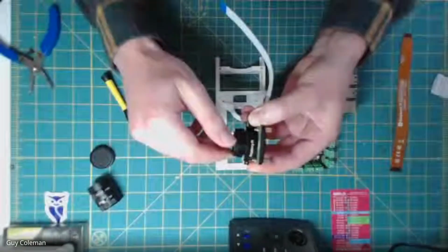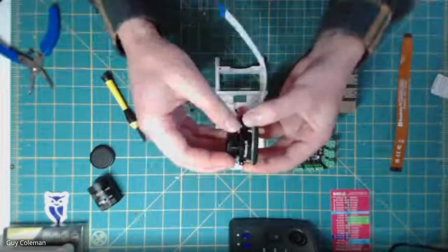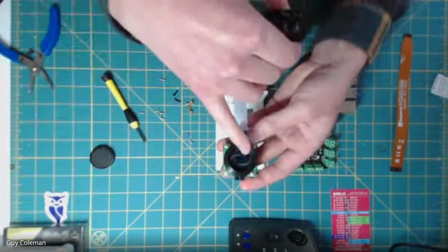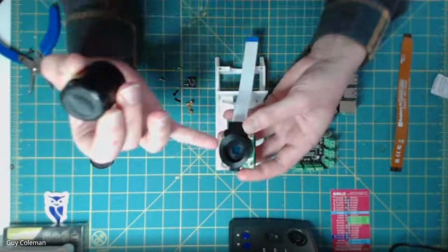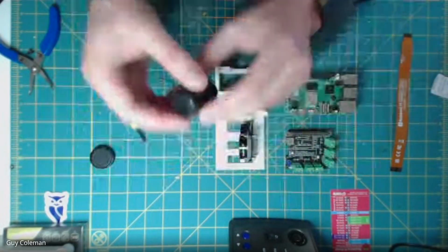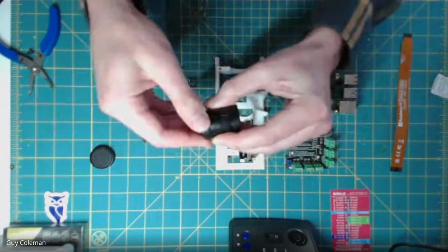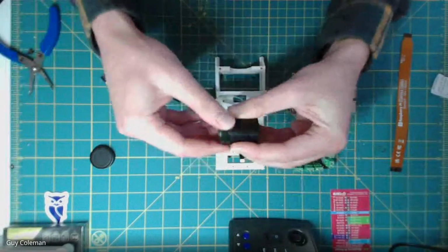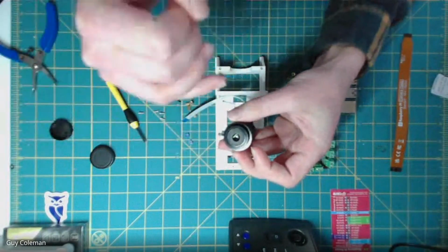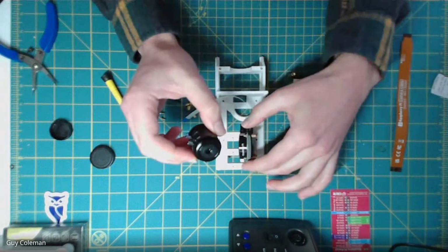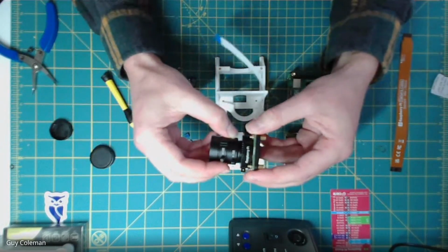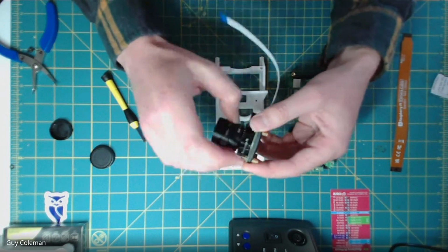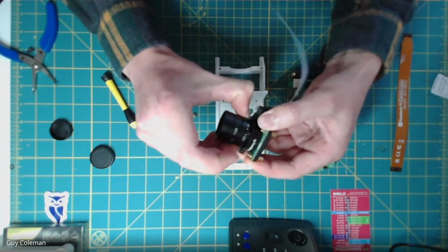So if you remove that, I have far too many of these lying around, and you can actually see the sensor. That's the imaging sensor underneath there. You don't want to get any dust or dirt on that, so I always try and keep it facing down. So the next step is to attach the lens. If you unscrew the lens cap, again, you want to avoid getting any dirt or dust on that, otherwise it will always show up in your images. And then tighten that down on here. You want to screw it all the way in so it's nice and tight and can't go any further.